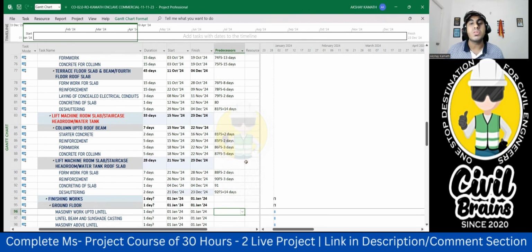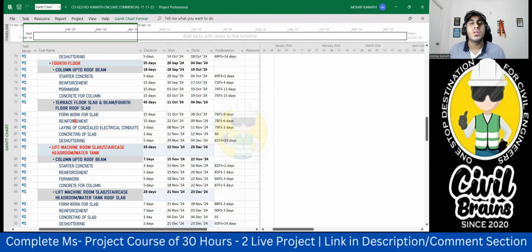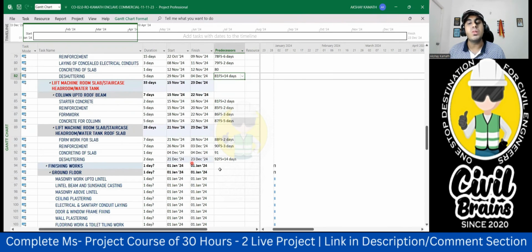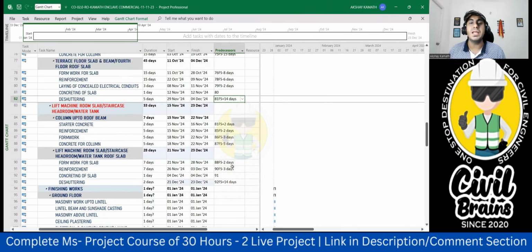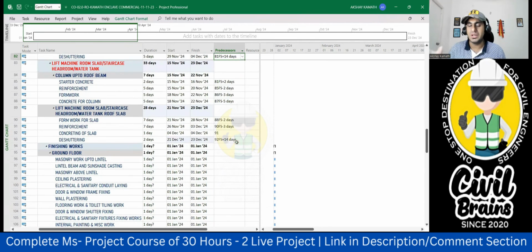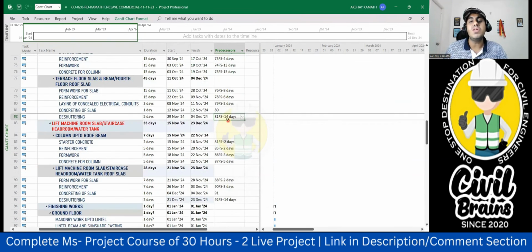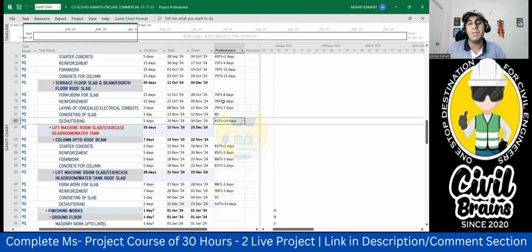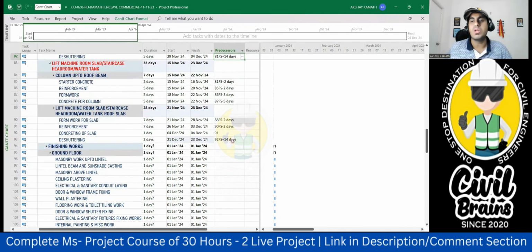One more thing. Suppose if here I had given 21 days, since it was a big slab, then for this small slab I could have given 14 days. But anyhow, here also I had given 14 days, so here also I'll give 14 days. You cannot remove the props and all before 14 days. At least 2 weeks you have to keep them there. That was the logic, since it's a small slab. But anyhow, I had made 14 there, so I'll keep 14 here.